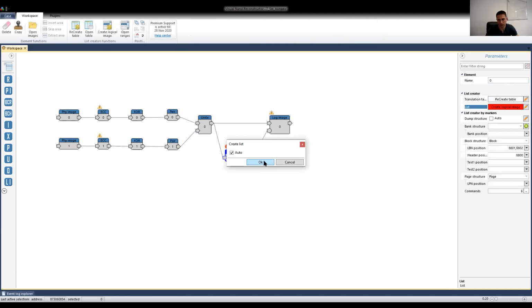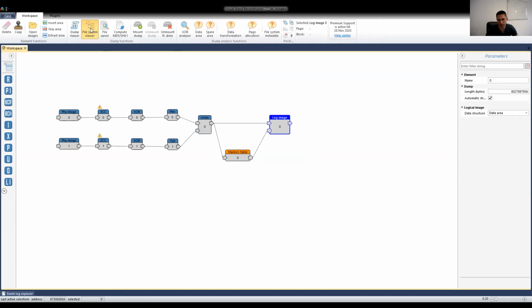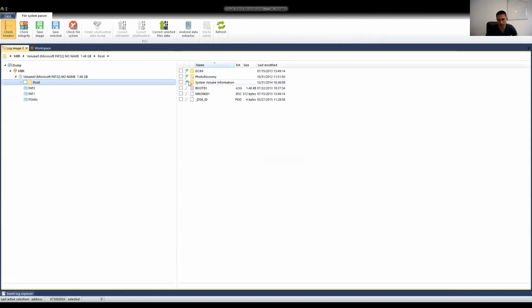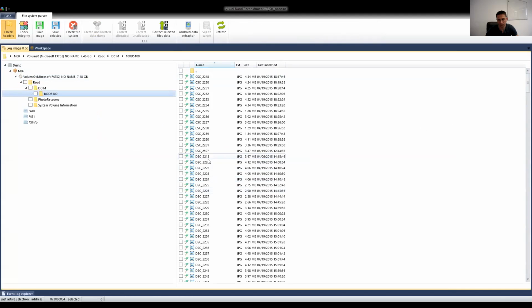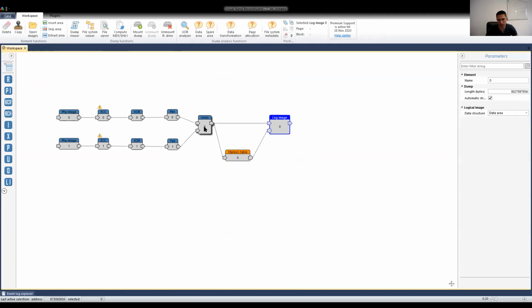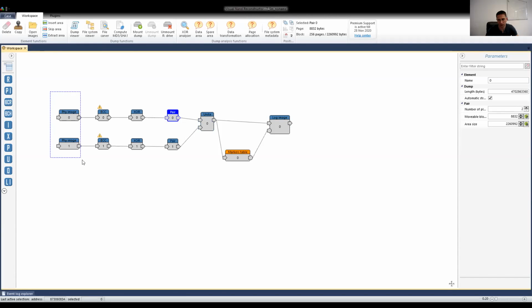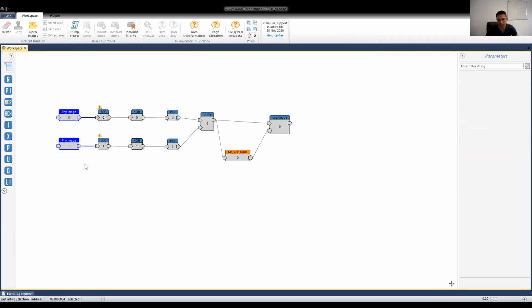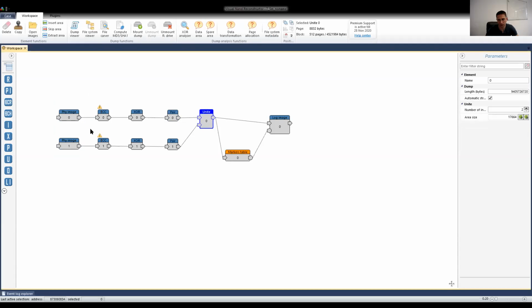In this case, it's already done, so I can open the case and see files. Okay, so this case shows multi-plane page allocation with 2 chips, and multi-plane page allocation was used on the chip level and on the planes level. So the controller used all possibilities to increase speed. Any questions about this case?